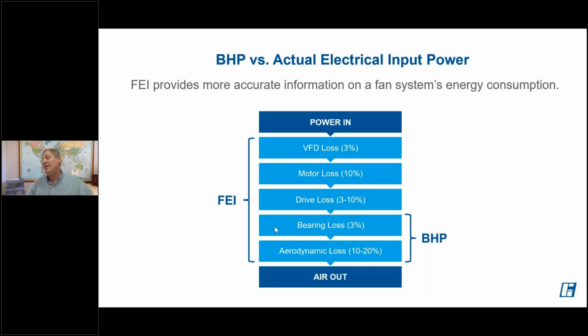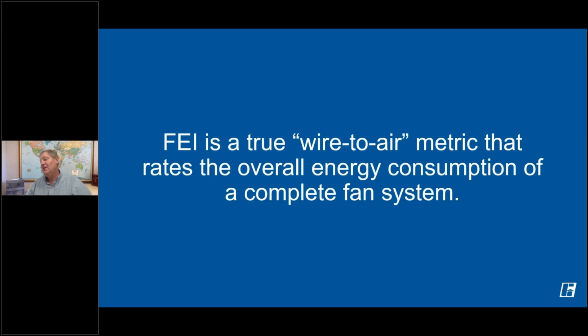All right. So again, from that standpoint alone, FEI is a much more robust and better way to make your fan selections. As I kind of said, FEI is truly a wire-to-air metric that rates the overall energy consumption of the complete fan system, not just the fan and bearings.